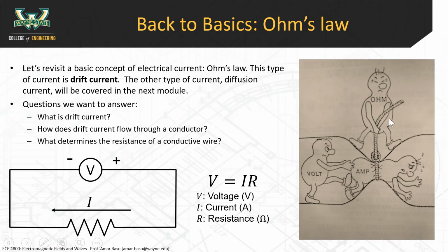So the way you can think about resistance is how much you're squeezing the charges, how concentrated the charges are in a certain area. Out here, the amps would be moving easily, but through this constriction zone, the charges are squeezed together, so there's more resistance, and that's why this small section of the trace has more resistance associated with it.